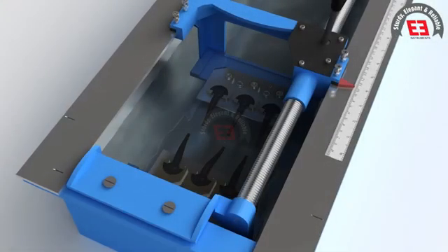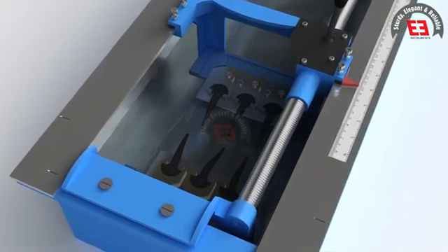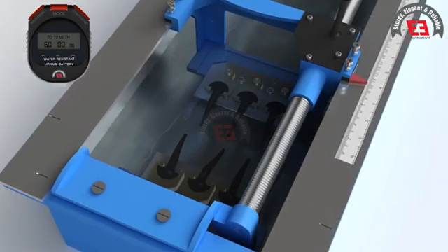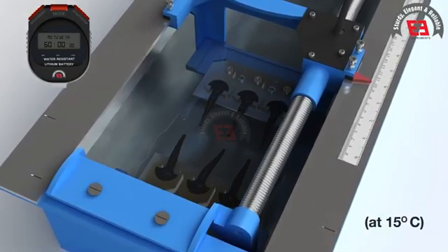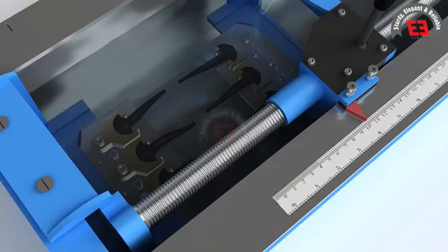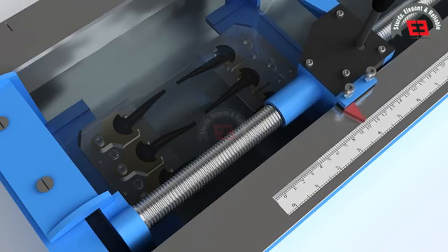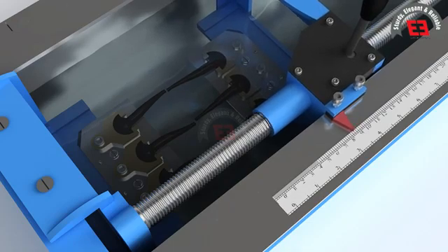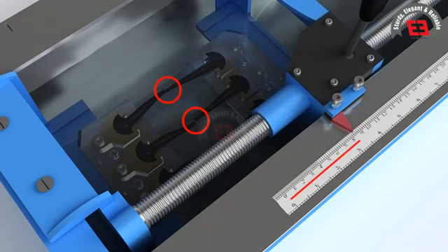The specimen is kept in the water bath in an undisturbed condition for a period of 60 minutes at the specified temperature of 15 degrees Celsius. After 1 hour, the elongated half of the specimen is moved back to the position near the fixed half of the test specimen, so that both pieces of the specimen just touch each other. The length of the recombined specimen is measured as d centimeters.